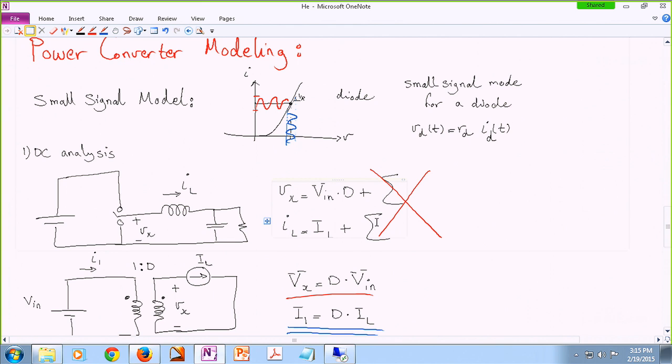A small signal variation comes in when my input voltage is changing gradually, something like that. Because I thought that small signal represents that whenever you have a perturbation in an input voltage or a load resistance, or something external to the circuit changes, that's what causes it. Yes, but those changes may actually cause some harmonic changes as well. So we are eliminating the harmonics and saying, yes, our input voltage may change as a slow, low frequency small signal variation, and it may cause some other harmonic somewhere else.